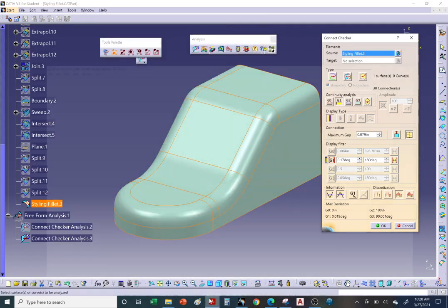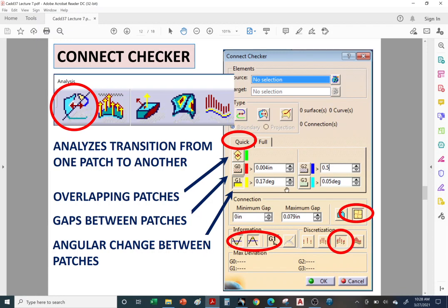Let's go back to the tutorial. Maybe I have it in here. Yep, here it is. So the lead surfacing expert in your department or somebody in the department will come up with the numbers that we're allowed to deviate from. So how much can we be off by and yet accept the results. Okay, so 0.17 seems to be what's acceptable if I remember correctly from my styling days for G1.